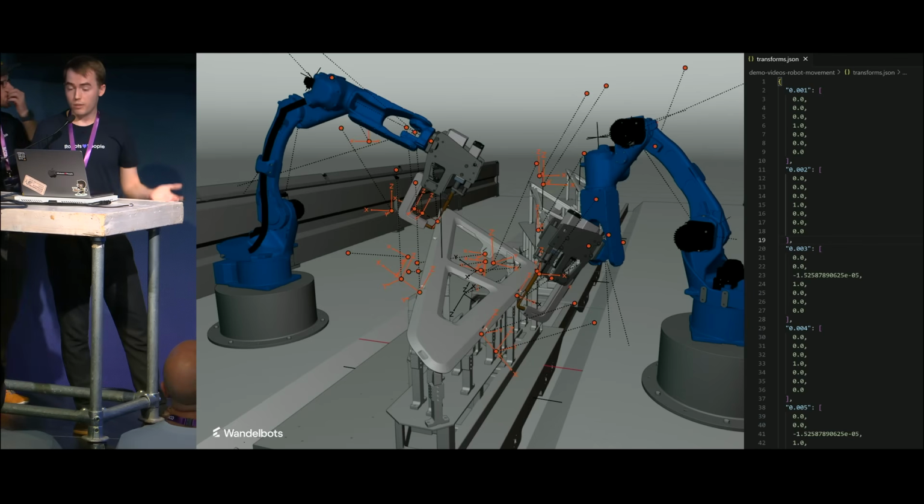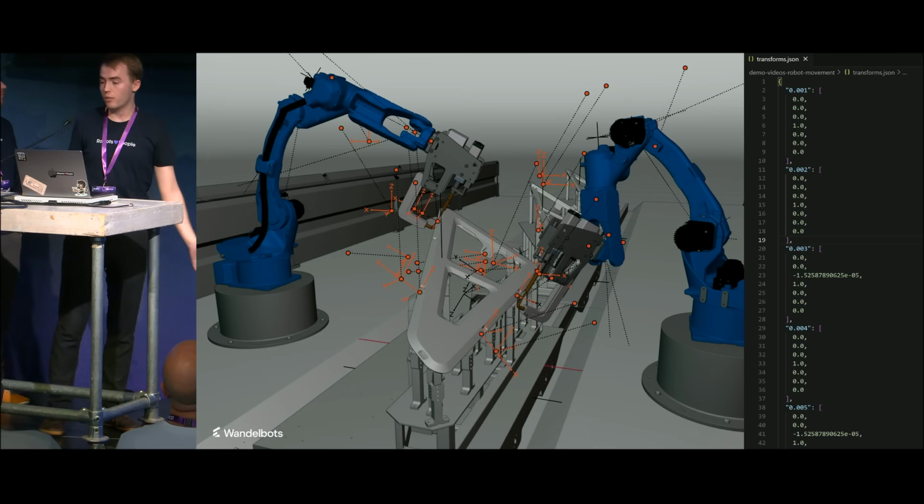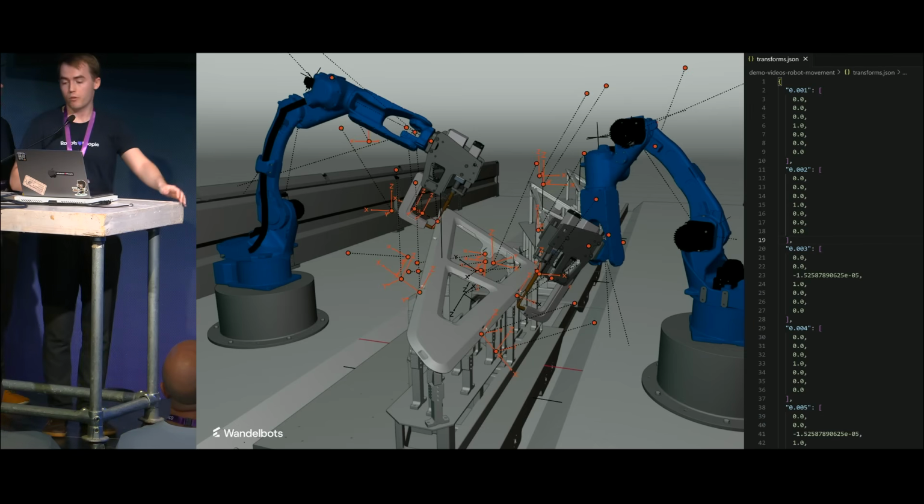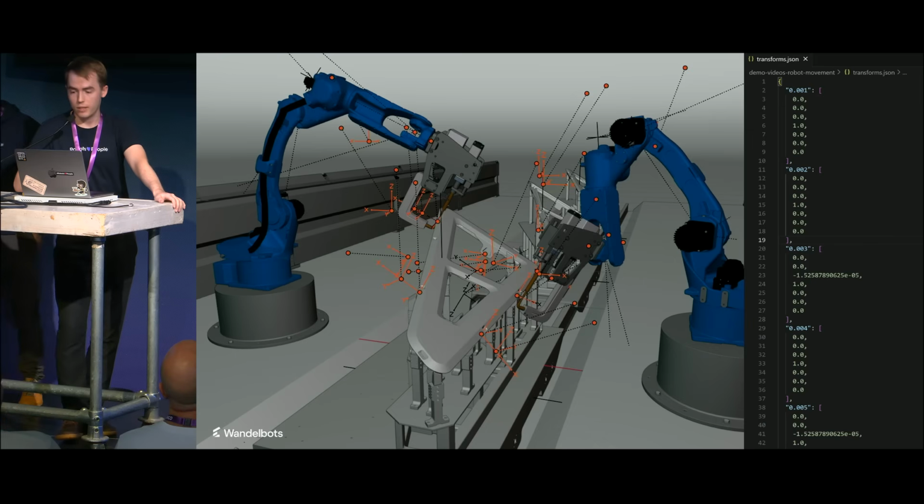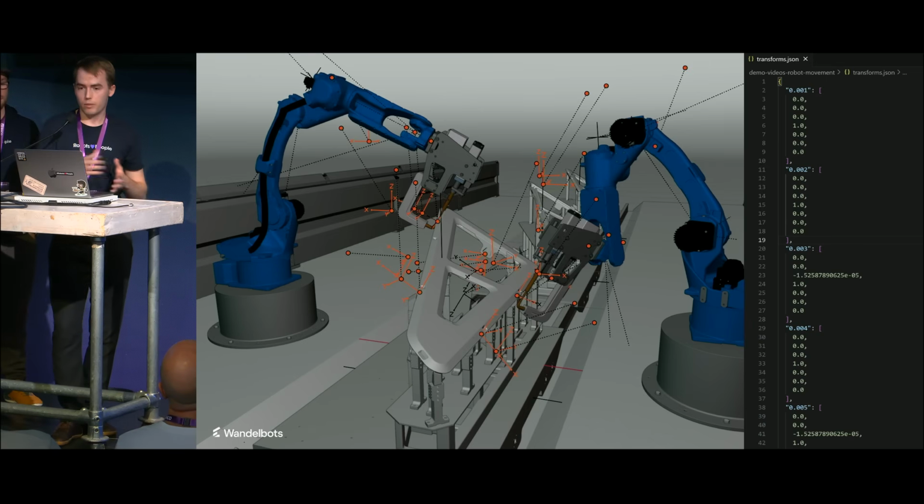There's a lot more to do until we actually get to robot programming and path planning. The scene planning, of course, begins much earlier than just plopping down some robots and starting. The first step generally is rough reachability testing by manually jogging. Jogging in this case means moving the tool at the end of the robot manually in directions X, Y, Z, as you might know. This is also something that we can do in Blender. As soon as you know what parts of your workpiece your robot can reach and what parts it can't, you can make a decision on robot placement. Maybe you even should consider a different robot with either a smaller or bigger reach.